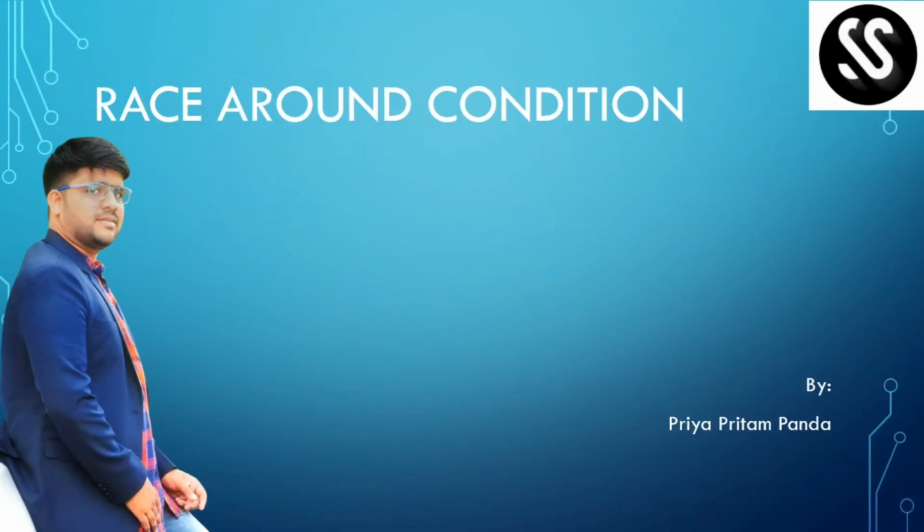In this lecture, we will study the race around condition, which is an important topic in digital electronics. We have studied the flip-flop, D flip-flop, T flip-flop, SR flip-flop, and JK flip-flop, right? D stands for delay flip-flop, T stands for toggle flip-flop, and SR is the set-reset flip-flop. One problem comes with the SR flip-flop: when S is 1 and R is 1, we are not able to predict the output. The output cannot be determined, which is actually overcome in the JK flip-flop.